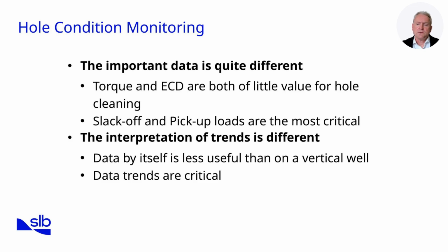For example, gradual increases in pickup weight can indicate cuttings accumulation, while sudden shifts may point to mechanical sticking or key seating. Unlike vertical wells, single point data has limited value. It's the trend over time that reveals the true condition of the wellbore. Because ERD wells are more prone to instability and cuttings transport issues, proactive monitoring is essential. Spotting problems early allows us to respond with circulation or conditioning before serious complications develop.